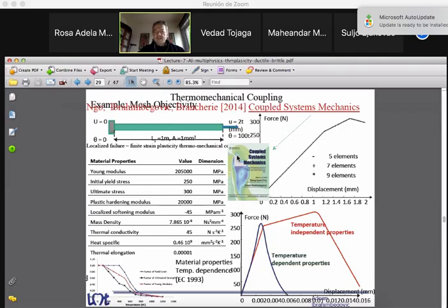So the idea is that there's a much bigger reduction with respect to very high temperature. You can see when temperature goes up to 600, 800, there's a really sizable reduction of these. And so you can see that as a consequence, the steel, which is a very ductile material at room temperature, let's say 20 or 30 degrees, when you go to very high temperature, ductility is completely lost.